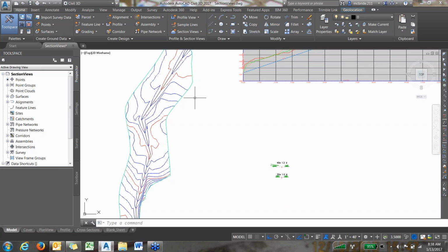The finished grade surface has on the outside the original grade contours, and on the inside where the alignment goes, it created a waterway section. You can see how it points everything upstream. That means I built a waterway into the surface. That's the only one I have turned on, and that's where we're at this point.